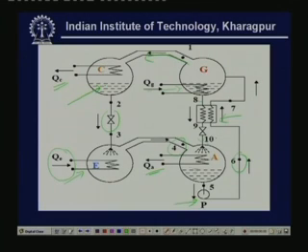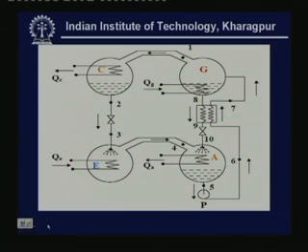Okay, and the cycle continues, the vapor goes to the absorber and the cycle continues, and the solution, which is now stronger in absorbent and weaker in refrigerant, at point 8 flows through the solution heat exchanger, then the expansion device, and is then sprayed into the absorber, so that it can again absorb the refrigerant vapor. Okay. So, again look at the points. Point 1 is the exit of the generator, where it is pure refrigerant vapor at high pressure and high temperature at the exit of the generator.